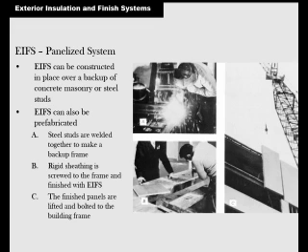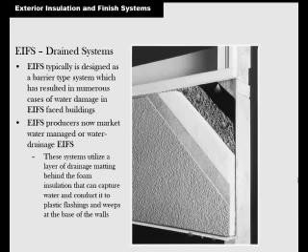So you can put this product over steel and masonry. Here you can see a panel going down there. It's very good for this kind of commercial, multi-story construction, but I wouldn't do it on a house. Here's a close-up look. It has a drainage mat, the insulation, and then the thin layer of a stucco-type material on the outside.